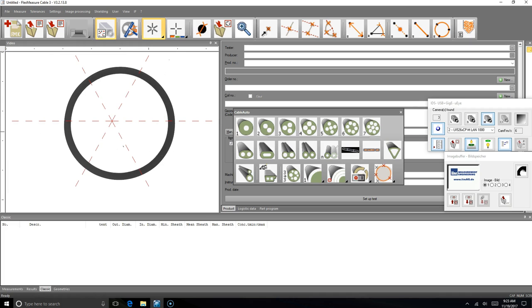So this is on the medium cable, and this is just a small sliver of plastic extruded tubing that we're looking at measuring the wall measurements on. In this case, it's treated like a cable. One conductor, what these icons mean right here: this is if you have one conductor in there, 2 conductor, 3 conductor, 4, etc. Now this one single conductor can also be multiple strands, but it's considered as one conductor.